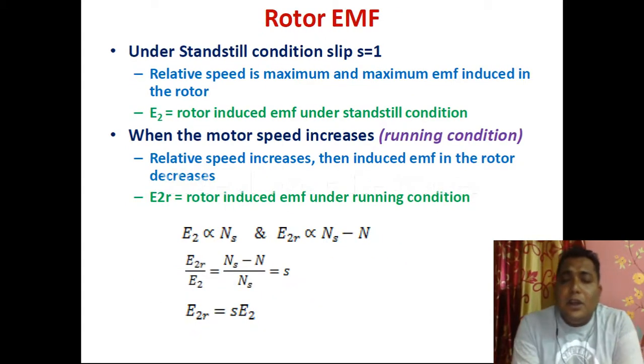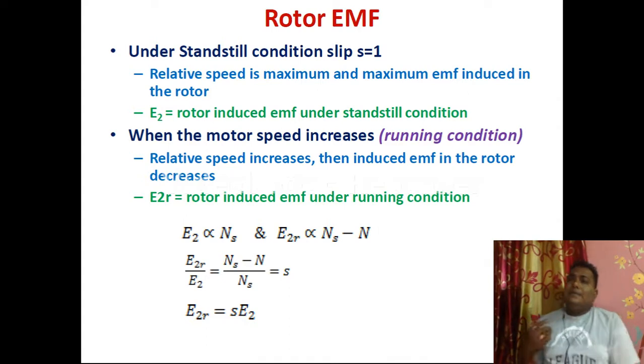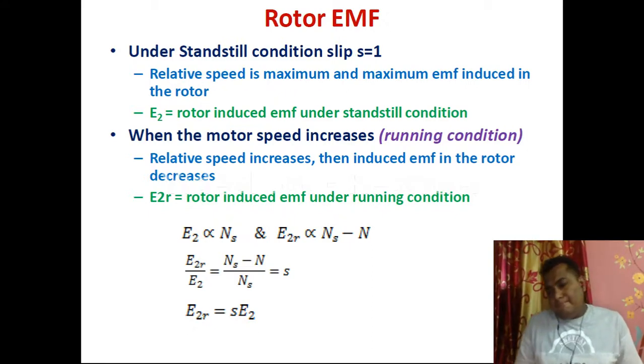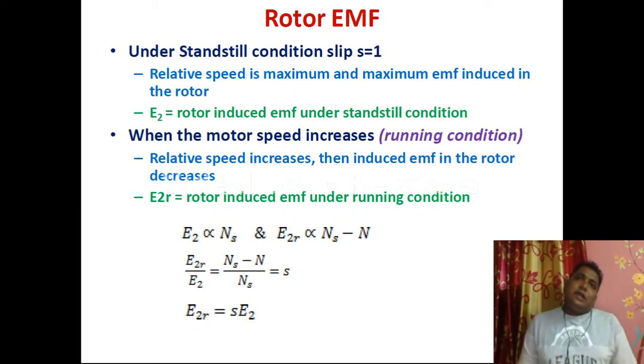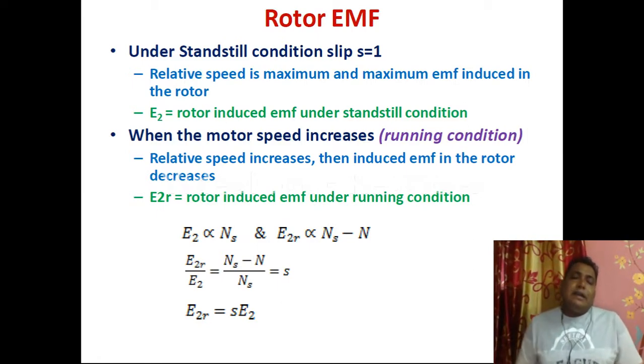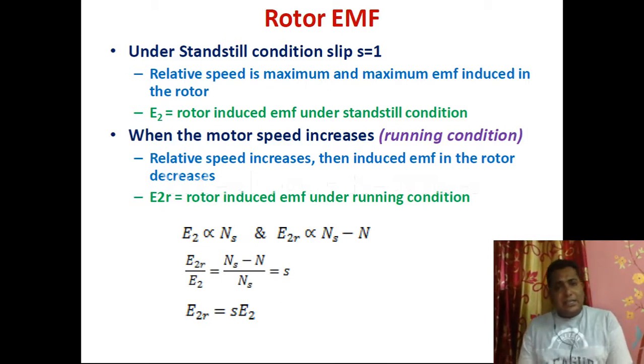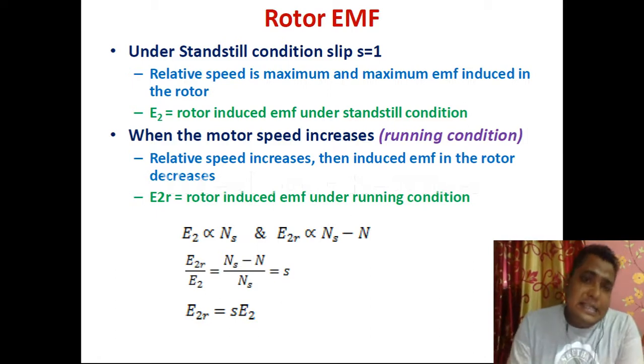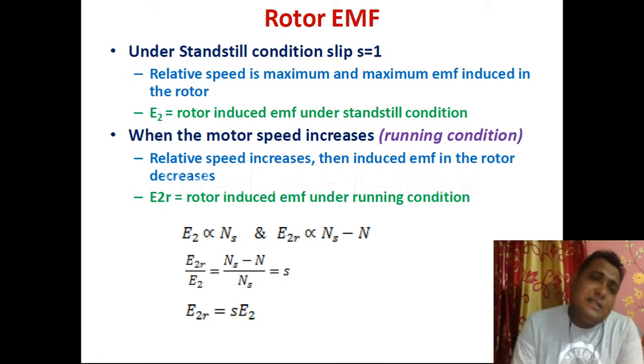Yes, rotor EMF. We have seen that in the rotor, the rotor frequency has the formula s into fs, that is, the slip into stator frequency. In this way we are going to find out the rotor EMF. Again, two conditions we have to consider: one is the standstill condition, and one is the running condition. First we are considering the standstill condition. So at standstill condition, what is written?